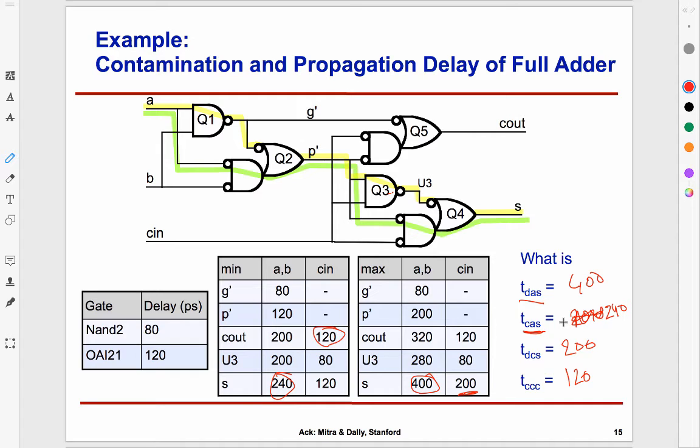So it turns out that in the logic that we commonly use in silicon, the so-called CMOS logic, gates are naturally inverting. That is, the simplest two-input gate is going to be a NAND gate or a NOR gate. And to create an AND gate, you have to take a NAND gate and add an inverter to it. So these are what are called inverting logics.